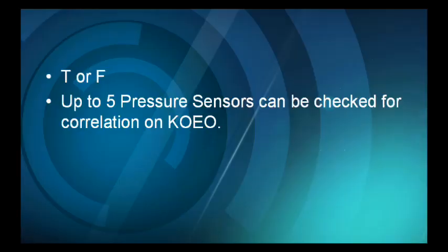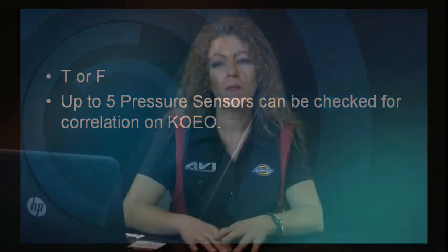True or false? Up to 5 pressure sensors can be checked for correlation key on, engine off. I'll give you some time to answer. It looks like 86% of our audience is going with true. Absolutely correct. It is true.